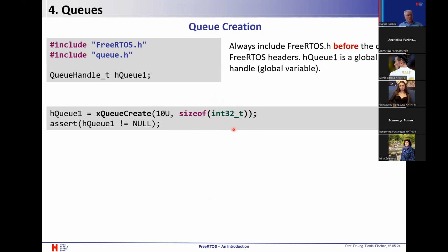In embedded programming, you should not use the native data types like int, short int, or unsigned short int. No, in embedded programming we are using these typedefs, and these typedefs are inside the standard int header file, stdint.h.